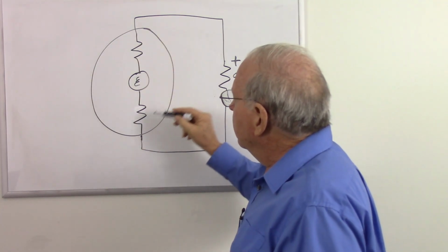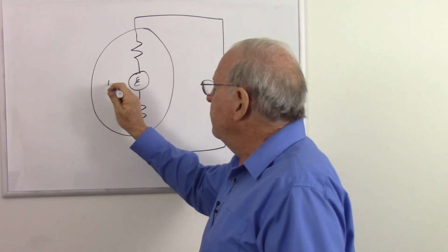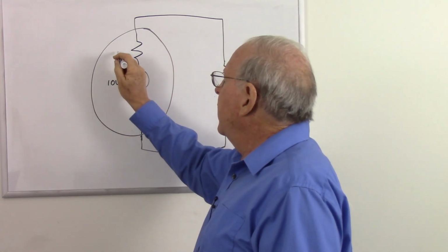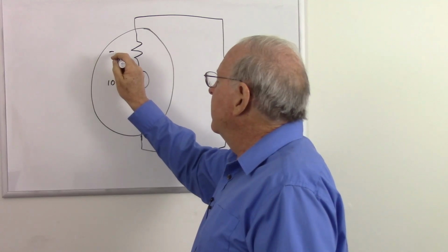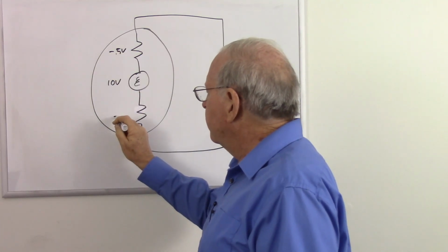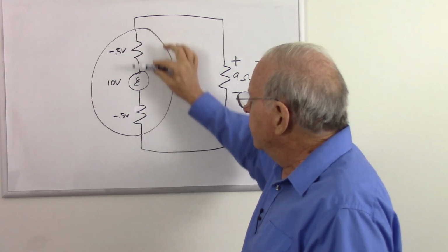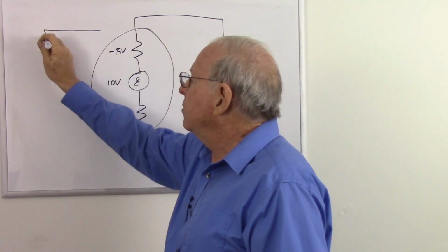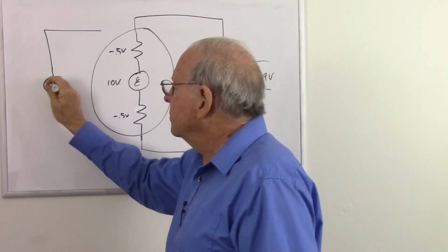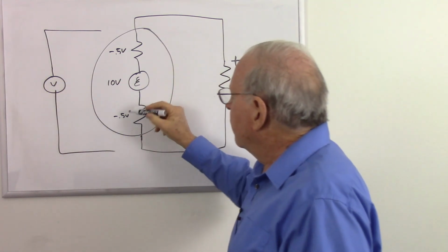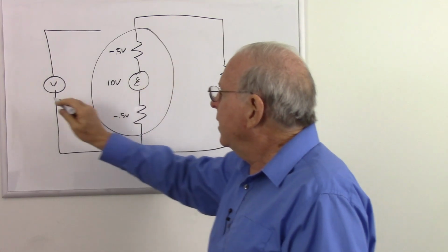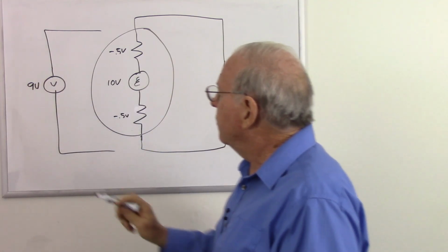And it's all in one piece. And so we have 10 volts of electromotive force, and we subtract 0.5 volts there, subtract 0.5 volts there. So remember, we started with 10, we lost half a volt, lost half a volt. So the total voltage across there is going to equal, start with 10, we lose 1, we have 9 volts.